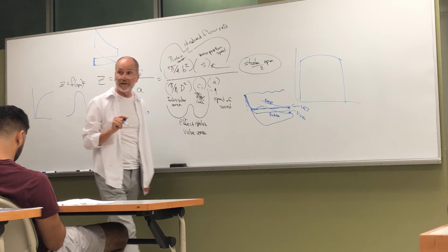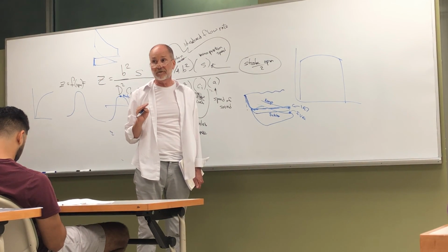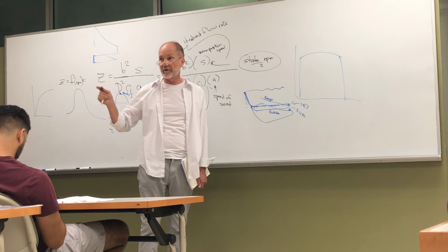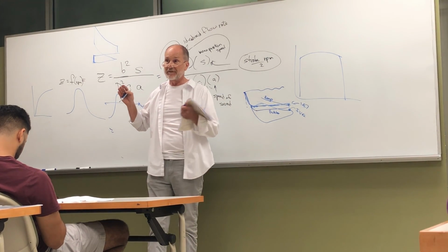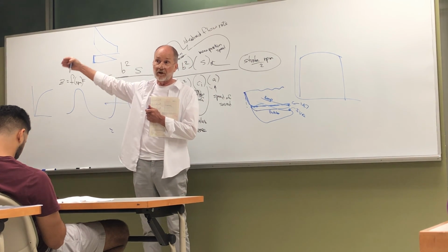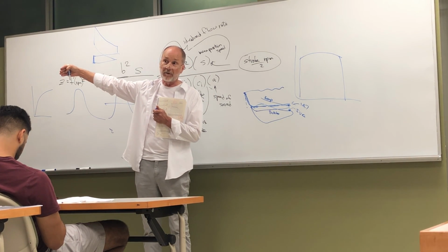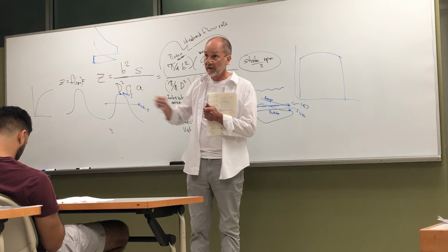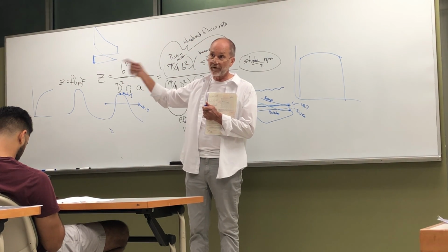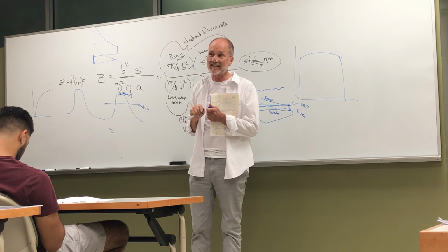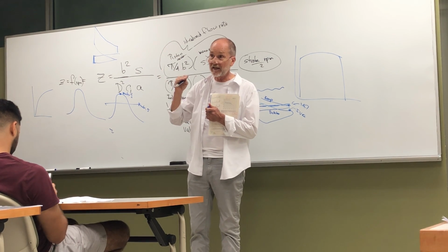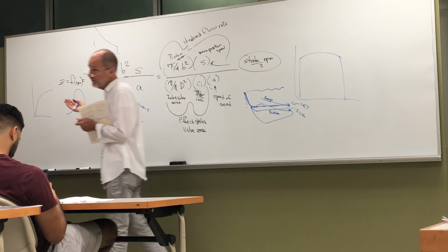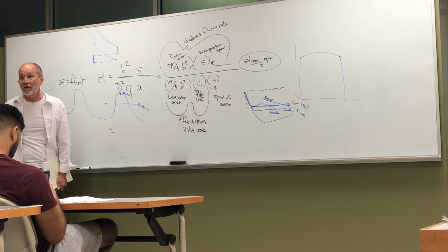Well, at low RPM, the resistance to flow is very, very small, because that resistance to flow is a function of velocity squared. By the time you develop a passageway that's operational at wide open throttle at 6,000 RPM, when you're down at 1,000 RPM, it's 6 squared, 1/36 at least. Then you cut the gas velocity because you close the throttle, which certainly brings it to 1 to 100.